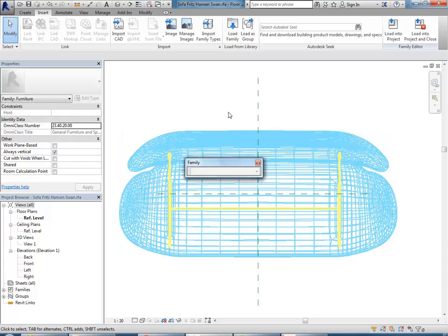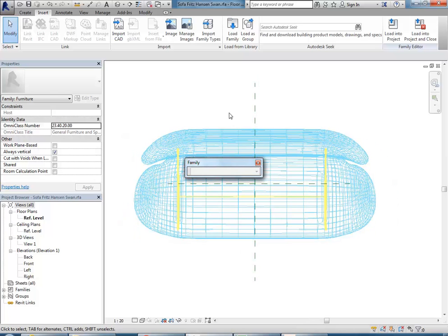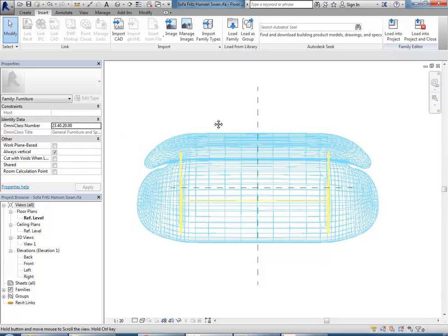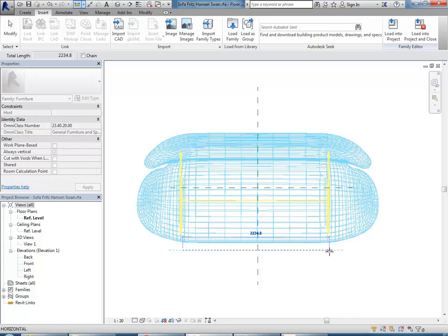It wouldn't be the right size. Probably, yeah. I mean, it would auto-detect, and I'd say there's a good chance that it would detect centimetres or something like that. But there is actually a unit setting, but it's a system setting that you can't get to with the vanilla version of AutoCAD. And it's strange. They did show it with ADT for a while, but now they've hidden it again. Which kind of makes sense because you don't need to know what AutoCAD thinks the units are as long as you know, and you just scale things accordingly.